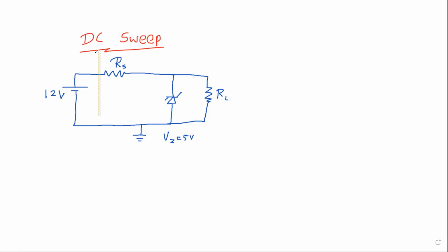What we expect from a regulator circuit like this is, even if our input changes, the output voltage we need to maintain at a constant level. So theoretically, what we expect over here is 5 volts, whatever the value you have. So you can connect the circuit like this, and you can measure the voltage here, and you obtain 5 volts.